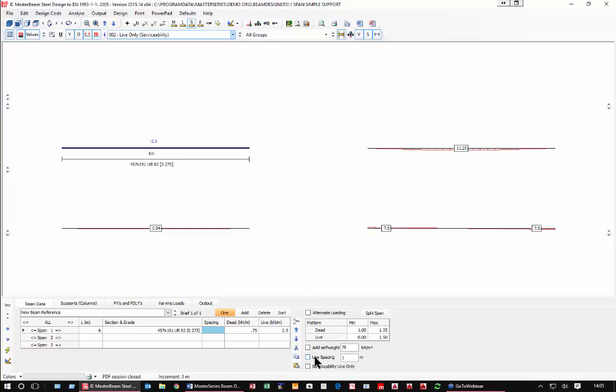If I now tell it that the spacing is 4 meters, that goes up to 10 because it magnifies it up. But I could say in this case the spacing was 3 meters here, and then you wouldn't bother with that. This one overrides all the other spacings, but you could have a different spacing for each different type of load. It saves you having to compute what if the spacing was 3.125 meters; you wouldn't have to compute all your loads up by that spacing.